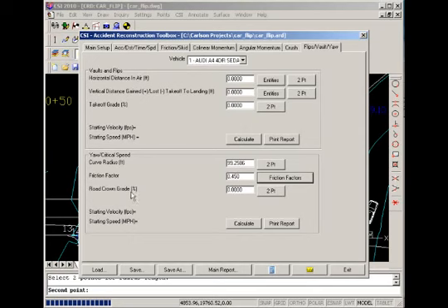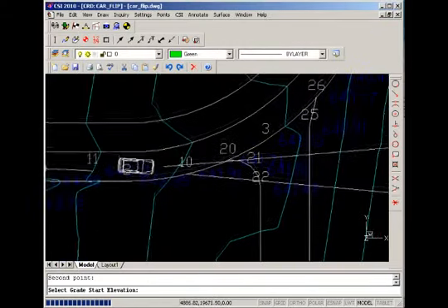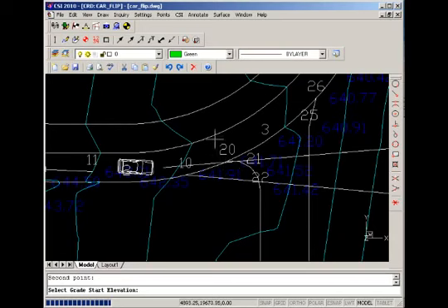Again, we have a 2-point option where we can go and pick the grade. To get the grade, we'll use our O-snaps. O-snaps are selectors that help you choose precisely specific locations in the drawing. If we type NEA for near, we'll have a yellow marker highlighted, and as we go near an object, that marker will snap to the location it thinks is best that you're trying to achieve.